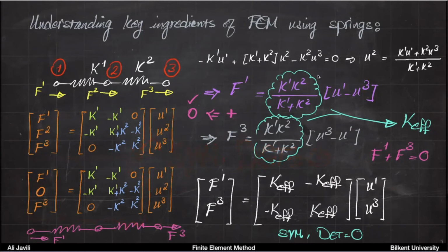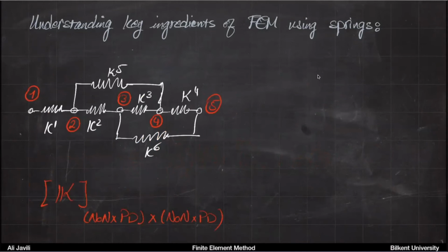So this is what we are talking about. This is the stiffness without imposing any constraint, without imposing any condition from boundaries. So we don't say where the forces are 0 or where the displacements are 0 or prescribed. So your raw stiffness, basically, not the stiffness after some manipulations.